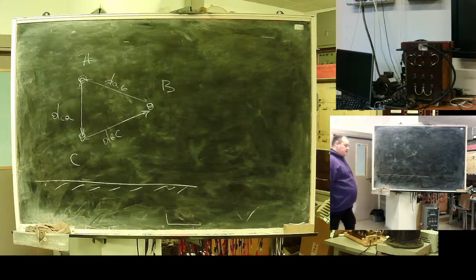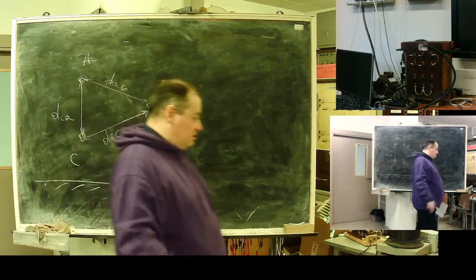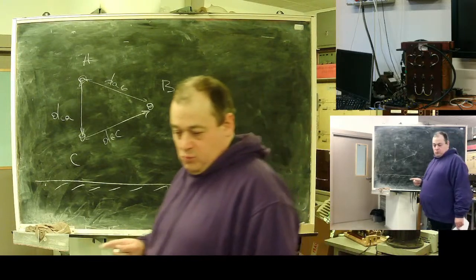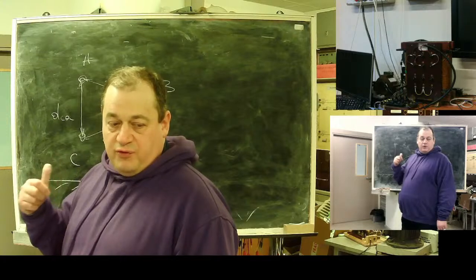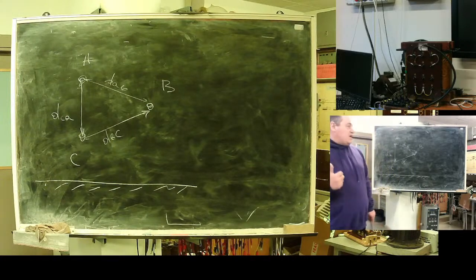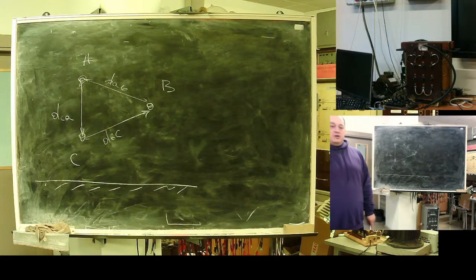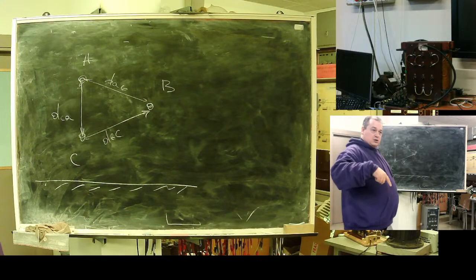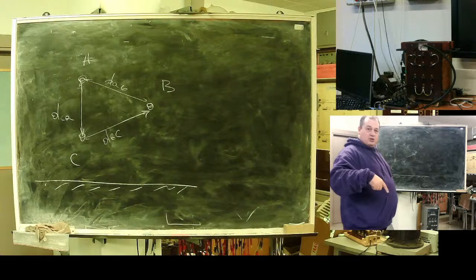It's an important moment. It's what's been done at the ground level, at the start of this theory. If you need high precision modeling, this trick will not work for you, because in a real high precision situation you will not have a full transposition cycle. And the distances between wires and their ground returns are not uniform, not equal.